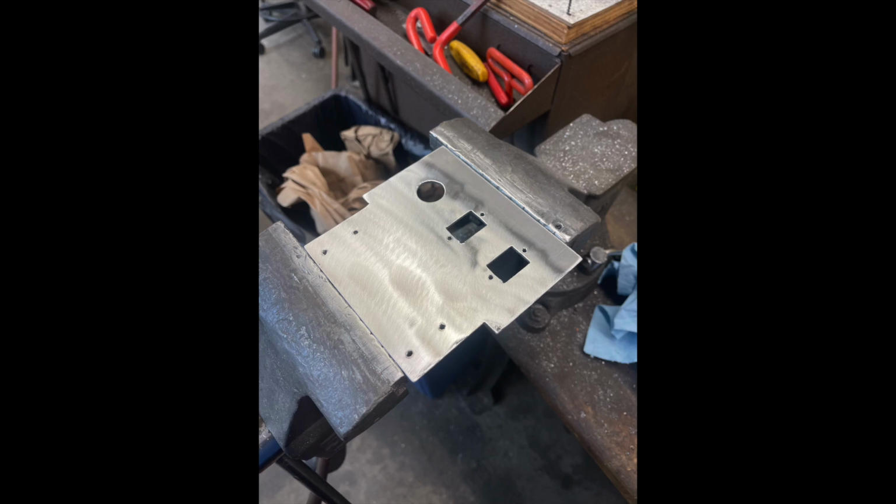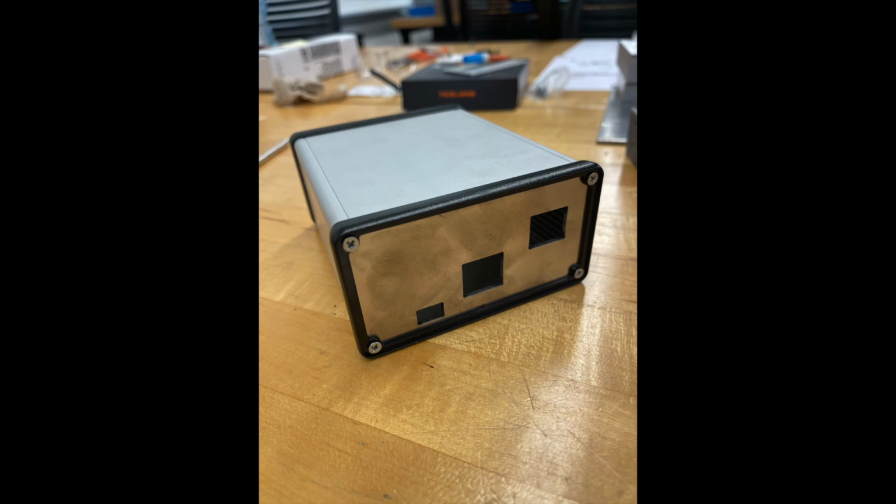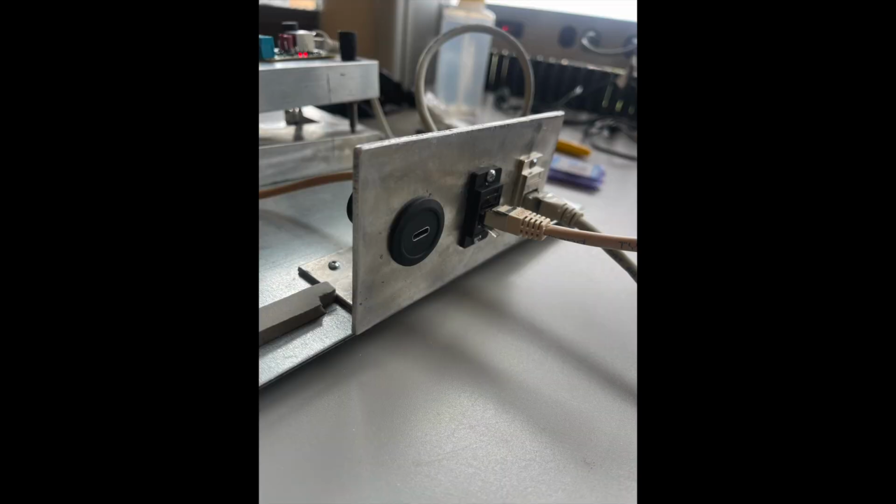Both the connector bracket for the large enclosure and the plates on both sides of the small enclosure were cut out using the Lincoln Electric Torchmate 4400, which is a CNC plasma cutter. In order to achieve the correct dimensions for all of the cuts, all components were first modeled in SolidWorks. For the connector bracket, once cut, the bracket was bent at a 90-degree angle so that it could sit under the enclosure lid while also laying flat against the enclosure to ensure shielding. All components were smoothed and polished to ensure a clean and smooth surface finish.